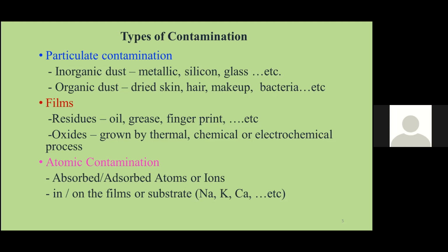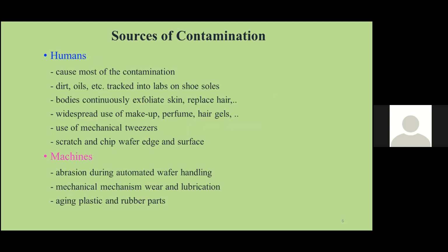Sometimes even when we touch the device, there is also contamination, because our hand has some kind of ionic contamination, like sodium, potassium, calcium. If we touch, or suppose this contamination is available in the room, this contamination affects the device properties or product quality.